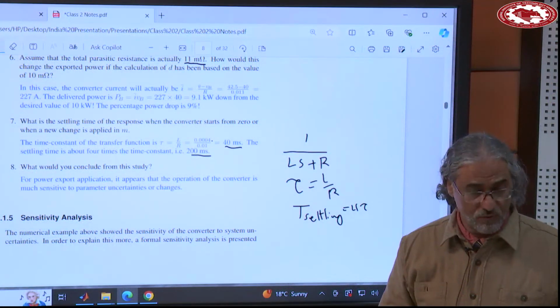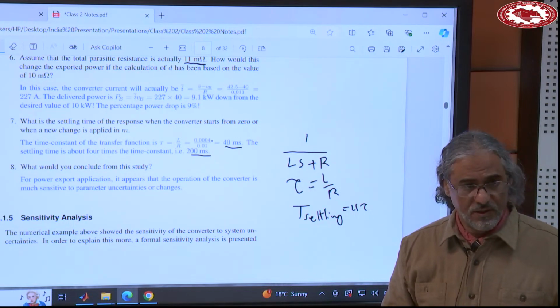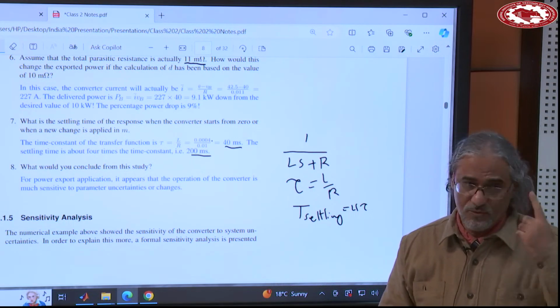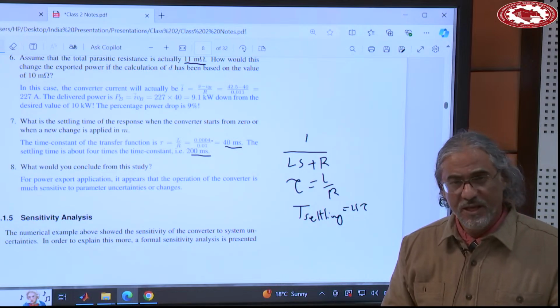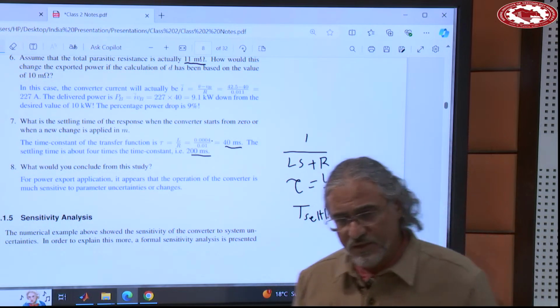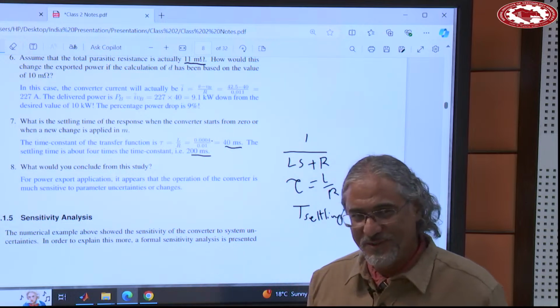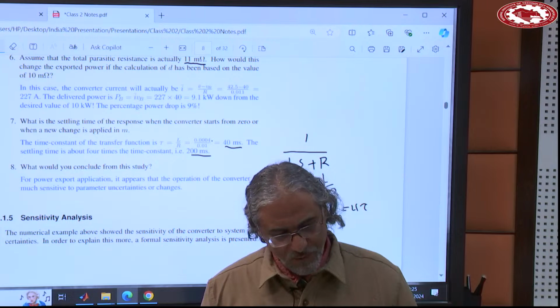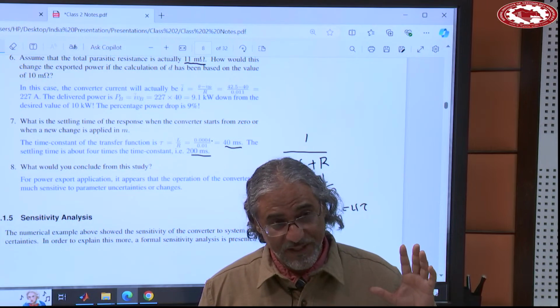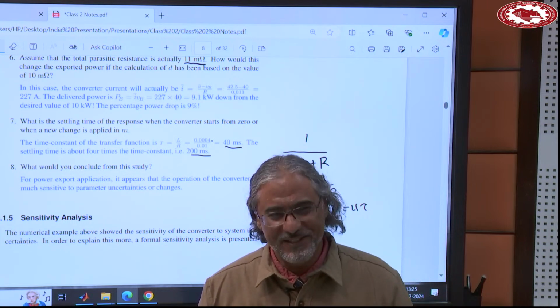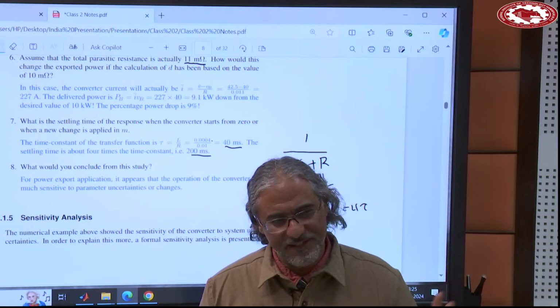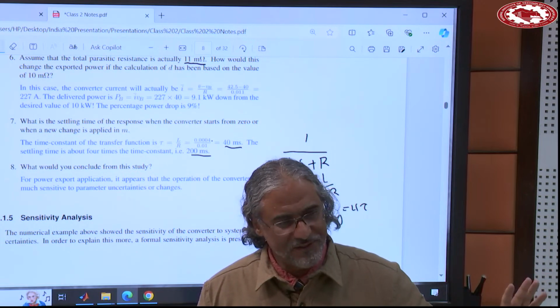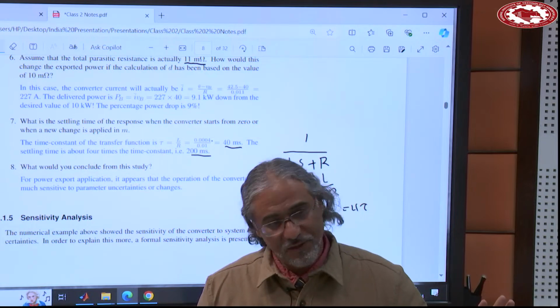Right, because the first one takes the responsibility for controlling the PV voltage. And we said it can only control one. It cannot control more than one. If there is a scenario, and at some point we will go into that, where you release the first converter from controlling the PV voltage, how? Again, you will see. There are situations where you can release it and say, don't worry about that voltage. Can you control this one on the other side?